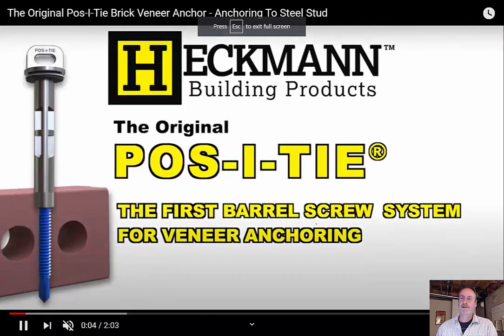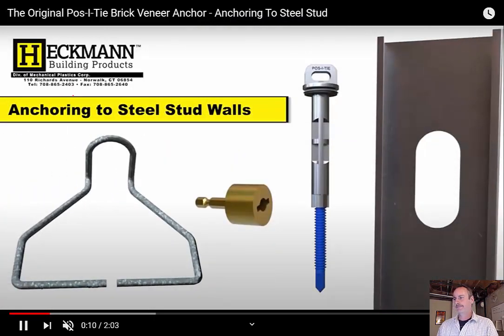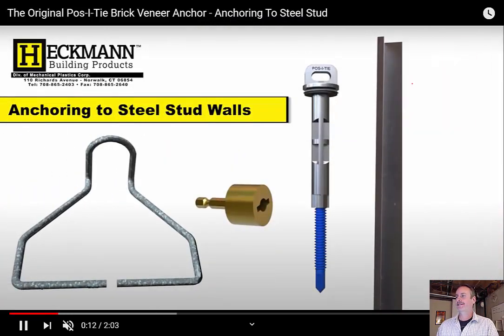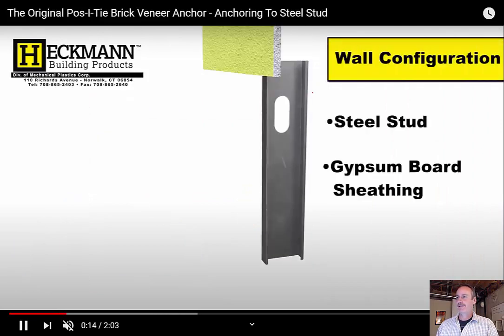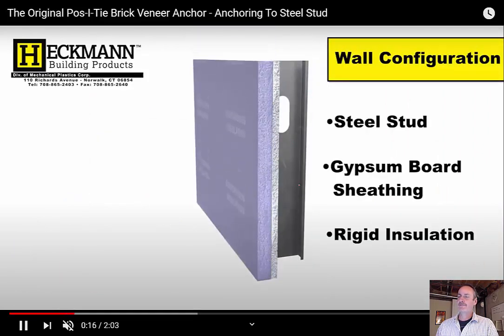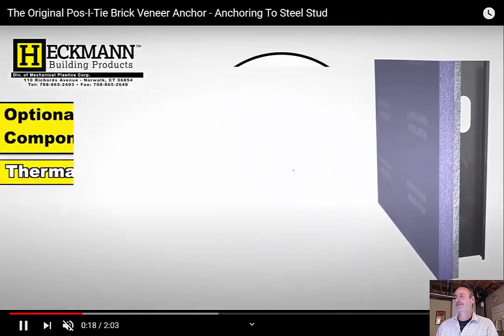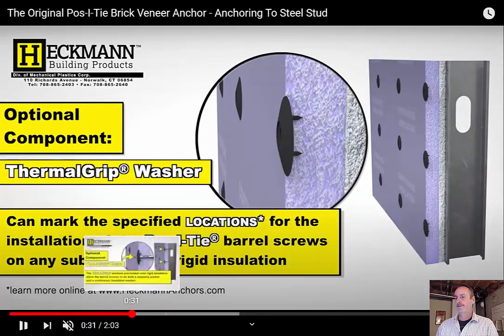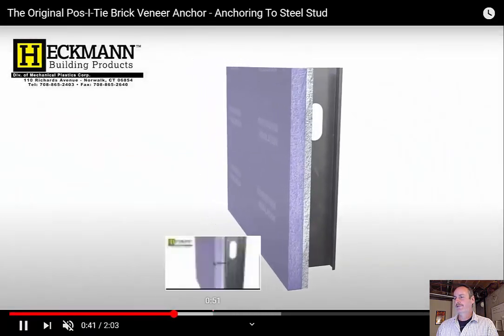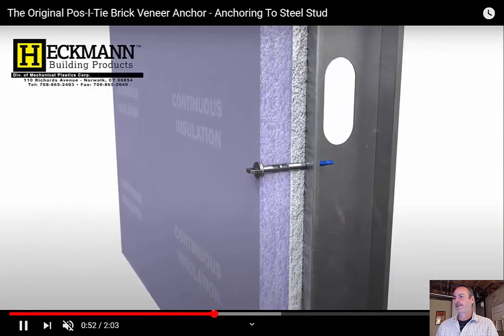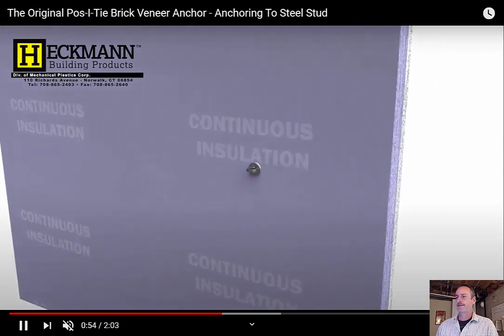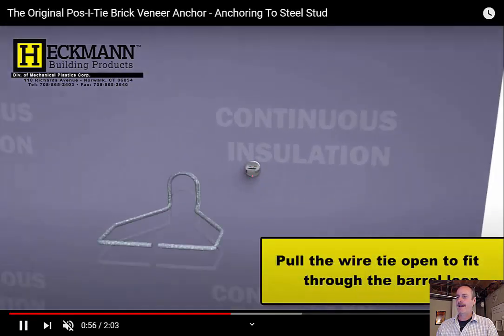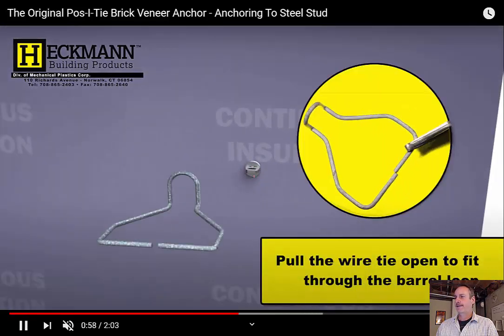This is a short video of how you might want to place these anchors. Now these are Posi Ties. It's not like I'm promoting this brand, but we did talk about these steel studs. And if I'm tying exterior brick to these steel studs and I have some insulation, one way that I can do this, let's just fast forward a little bit, is I can screw in this anchor to the steel stud. This has a little end out of it that then I can tie this